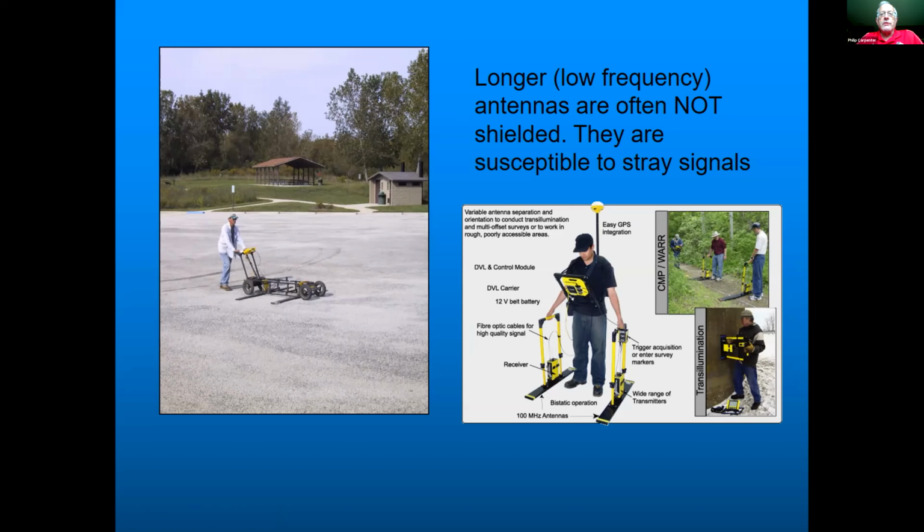So you need separate antennas like this, 100 megahertz. If your antenna is really small, you're probably above 200 megahertz, and you don't want that for landfill work.